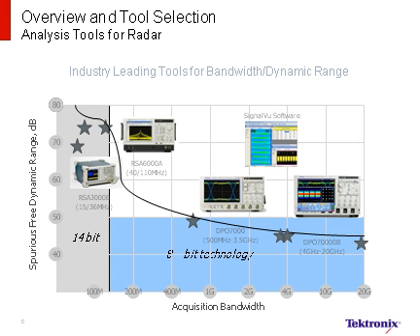Historically, measuring radar pulses has often required multiple instruments: spectrum analyzers for frequency, vector analyzers for IQ vector signals, signal source analyzers for phase noise and microphonics measurements, oscilloscopes for timing, average and peak power meters for power measurements, and frequency counters. Tektronix spectrum analyzers and oscilloscopes use IQ vector acquisition for time sample data, enabling the correlated time and frequency information with the highest combination of bandwidth and dynamic range.